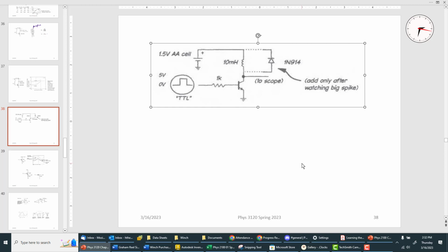And this has to do with the fact that as soon as an inductor sees a voltage, it instantly produces a reverse voltage of the same magnitude. In fact, if you do the math, it's infinite when you do the derivative. And in principle, it goes very high, but there's always a delay in the measuring and such.